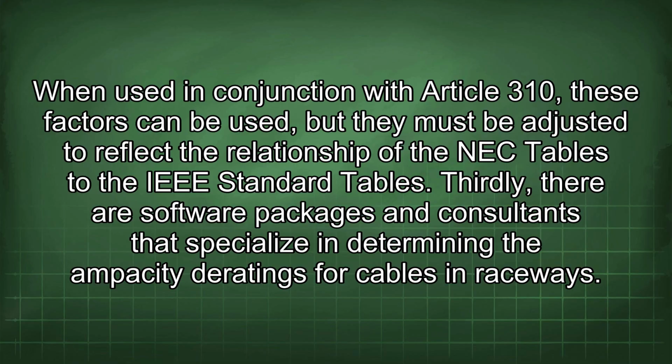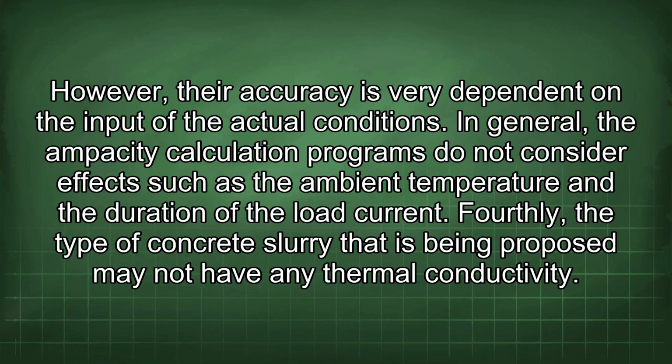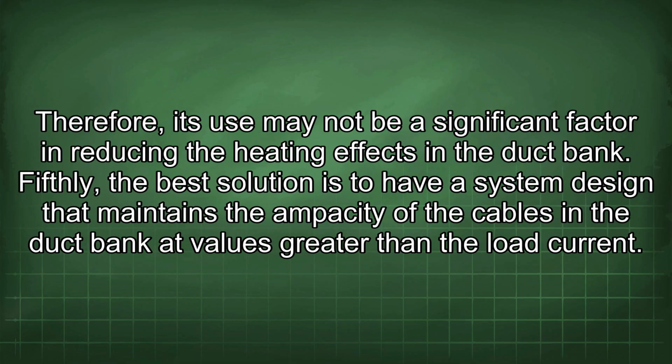Thirdly, there are software packages and consultants that specialize in determining the ampacity ratings for cables and raceways. However, their accuracy is very dependent on the input of the actual conditions. In general, the ampacity calculation programs do not consider effects such as the ambient temperature and the duration of the load current. Fourthly, the type of concrete slurry that is being proposed may not have any thermal conductivity. Therefore, its use may not be a significant factor in reducing the heating effects in the duct bank.